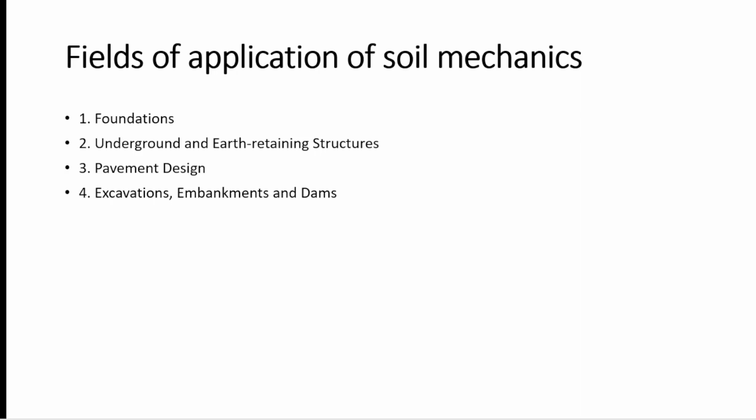Lastly, one application is excavations, embankments and dams. Excavations require the knowledge of slope stability analysis. Deep excavations may need temporary support timbering or bracing, the design of which requires knowledge of soil mechanics. Likewise, the construction of embankments and earth dams, where soil itself is used as the construction material, requires a thorough knowledge of the engineering behavior of soil, especially in the presence of water. Knowledge of slope stability, effects of seepage, consolidation and consequent settlement, as well as compaction characteristics for achieving maximum unit weight of the soil in situ, is absolutely essential for efficient design and construction of embankments and earth dams.